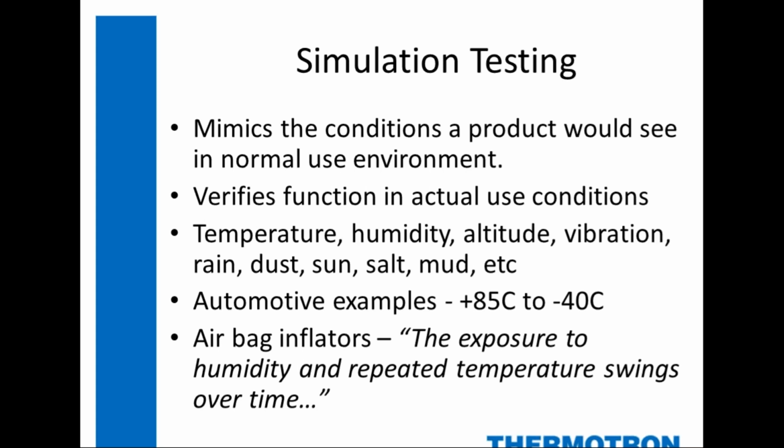And I know in the news lately, one of the big ones has been the huge recall of airbag inflators. And I think it's up to almost 50 million cars that are recalled now. And that root cause of failure was that chemical in there was exposed to high humidity levels and repeated temperature swings over time. So a combination of two different types of environments or stresses. So the takeaway there is it's really important when you're making a product to have a real good understanding of all the different types of environments or stresses that it'll be exposed to.